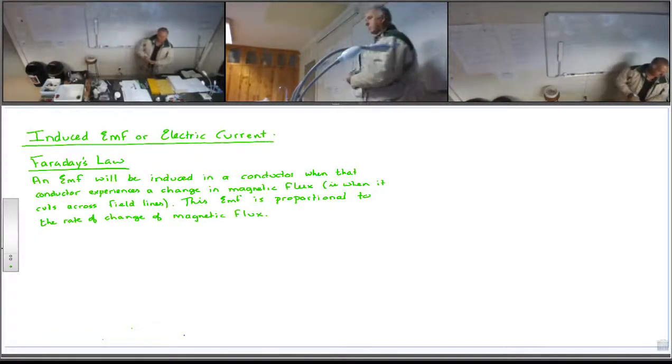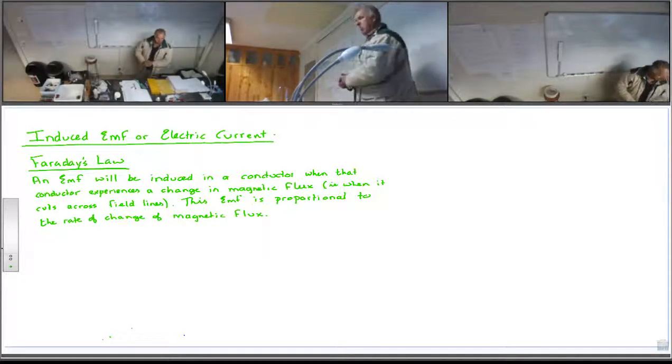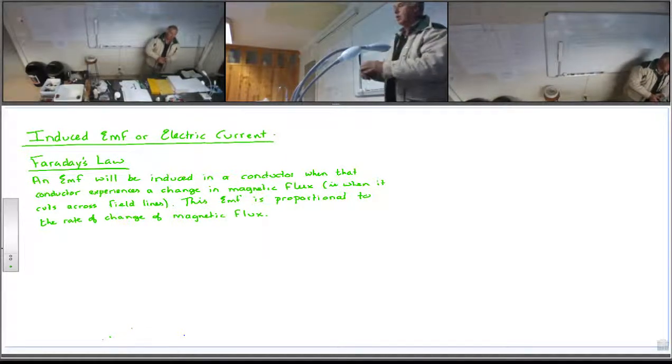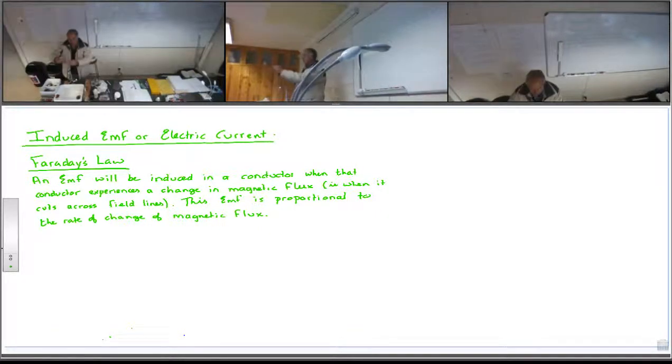Yes. Move the magnets. No problems. You get some dynamos where instead of having a coil that spins around, normally you've got a magnet, and then in between your magnets you've got a coil that you turn with a handle, like that one that we use inside to shock people. You've got a coil that turns around with two magnets surrounding the coil. Others have got a coil of wire, and when you turn the handle, you actually turn a magnet inside the wire. So as long as the one changes relative to the other.